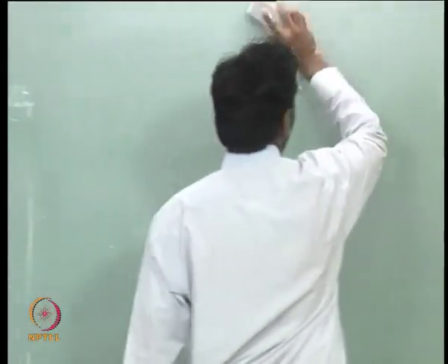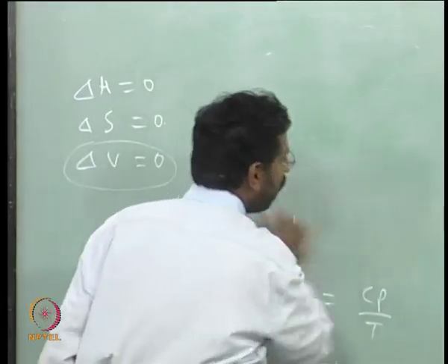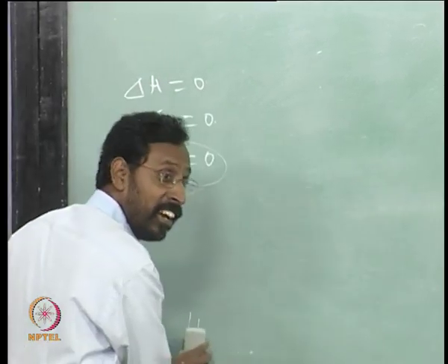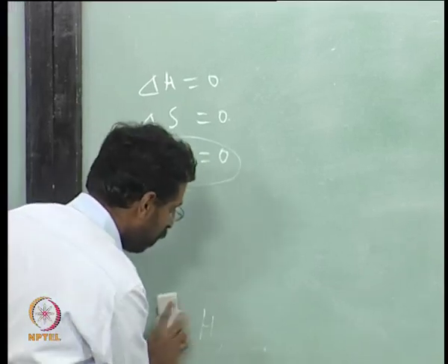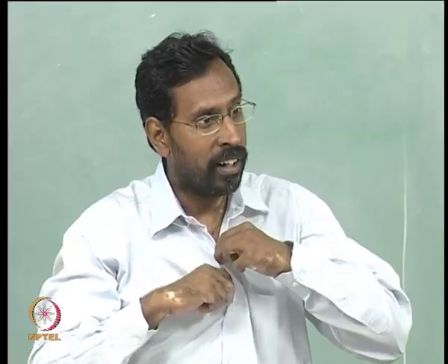Glass ceramics are again like nanocomposites, where you try to crystallize a little bit and get crystals inside the glass, so that it is like a composite. So that is again basically for the kind of applications that I was talking about, where you want to make tough glasses.